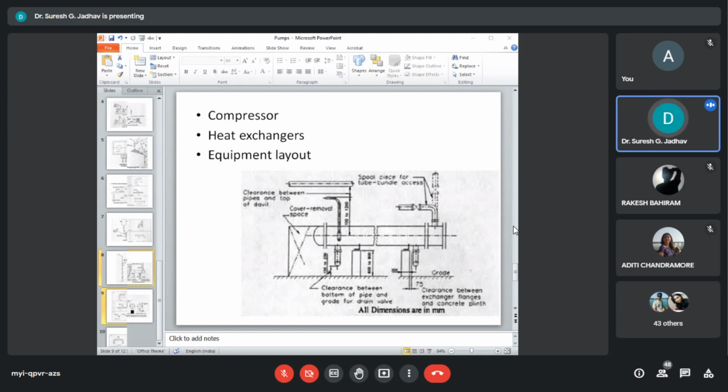So you can see these kinds of arrangements in compressors. We have to avoid back pressures and avoid vibration due to pulsating flow. Then we can modify the system using bends instead of elbows, angular inlets instead of laterals, smooth junctions instead of head-on opposing flow, and streamlined end of header arrangement instead of dead end headers.